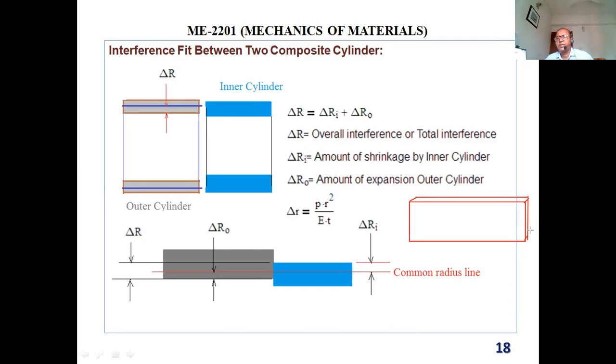Then you roll it, then you do the welding around it. Like this is a paper, this is a sheet. Now this sheet, you roll it, do the welding right over here and in both caps, then you have the pressure vessel, right?